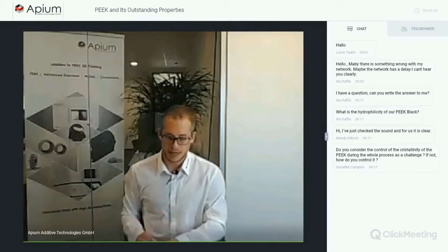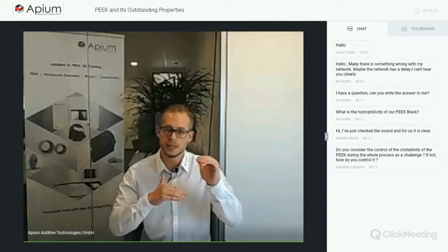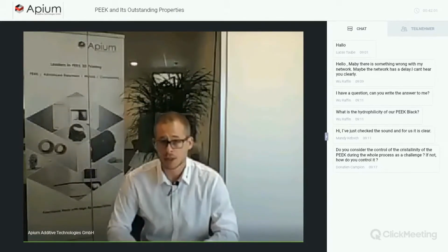Okay, more questions. Do you consider the control of the crystallinity of the PEEK during the whole process as a challenge? If not, how do you control it? I hope I have already answered this question during my presentation with the play of the zone heater, the heating bed, and the nozzle. So these temperatures all together play a critical role for the crystallization.